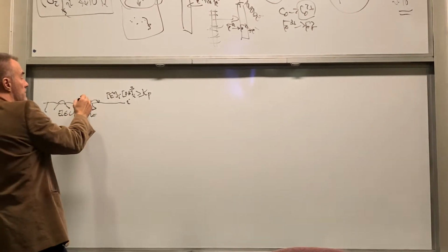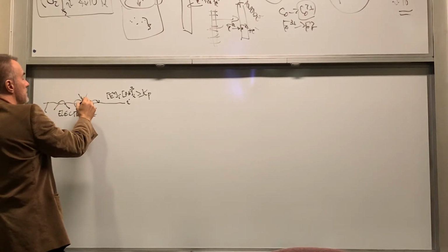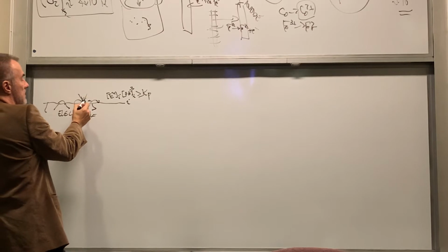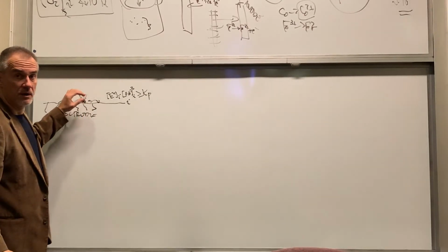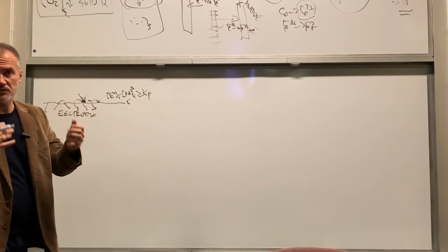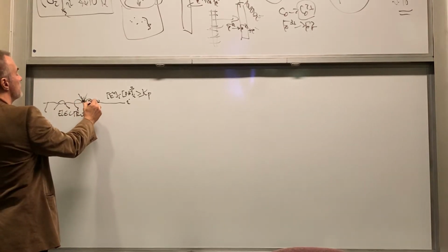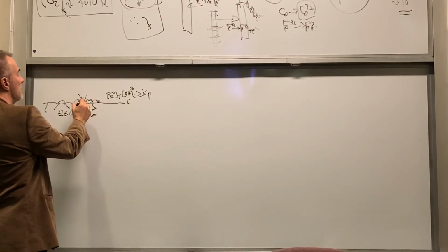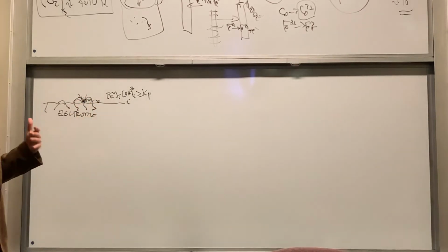Now, this oxide phase will eventually start to grow too and get a little bit bigger, but because it covers the surface, the electron transfer through this oxide will be much more difficult because iron hydroxide is not really conductive. And so what's going to happen is that surrounding nuclei of metallic phase will outgrow this and eventually trap it in the deposit.